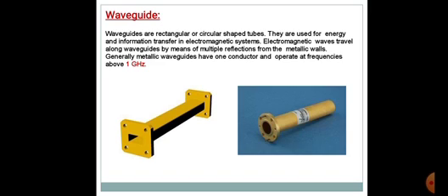Like I have told you, any antenna can't be directly connected to the transmitter section. So before connecting the horn antenna with the transmitter section, we need to fix a device in between, and this structure is called the waveguide, a medium used to transmit power from the transmitter section to the antenna section.